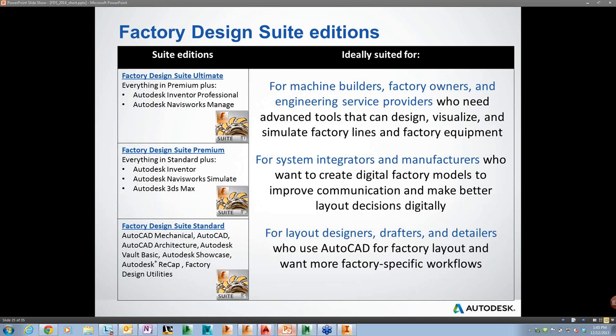Some other great tools that it also includes that we didn't show today would be something like Autodesk Recap. What Recap allows you to do is better capture those facilities. As we talked about the manual information and creating that documentation, Autodesk Recap allows you to work with point cloud data. So point cloud data, being able to go out, take a scan or multiple pictures or multiple scans, and create actual points of the physical representation. A lot of times in those brownfield facilities, you can capture the as-built state of that facility.